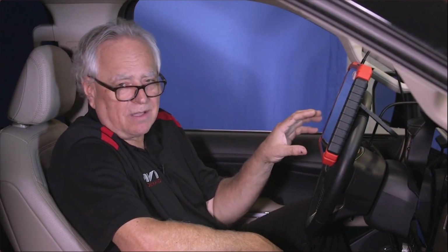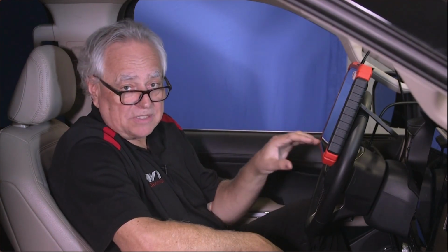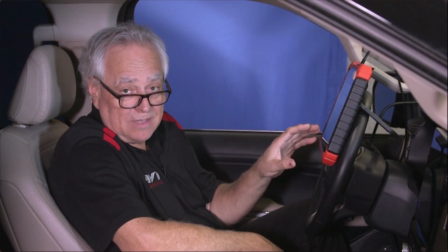Now remember, we talked about having a problem with the CAN bus. That'll show us that we have a problem, and that will be affirmed here. Anytime I do a test on a vehicle, I like having at least 2 or 3 tests that show that I've got a given problem. Then I can be pretty assured that that's my problem. So this is a test that you should never skip. Now some people think, well, this takes time because they remember their old scan tool, but hey, you've got these newer vehicles and such, and you've got this scan tool, it works pretty quickly.